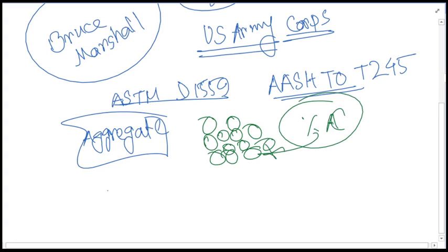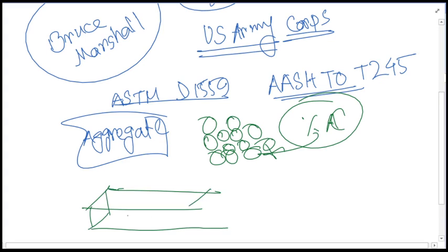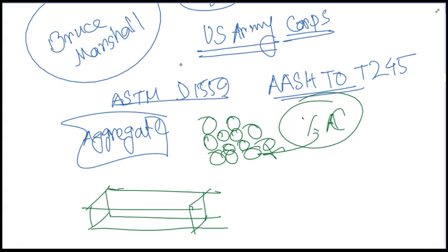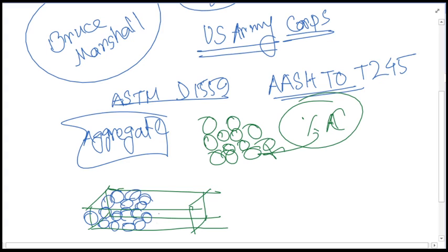used with this. As we know, if I give an example of a flexible pavement, consider this is a segment of highway. To construct this pavement, we need what? We need different aggregates. Different types of aggregates with a particular gradation will be available there. These aggregates will not be combined together if we don't use any asphalt content. So we need to add asphalt content as a binder, so that all the aggregates are bound together, and it will exert some strength to the roadway, and that's why while traffic is going over there, it will be able to resist the loads. And that's why we need asphalt.